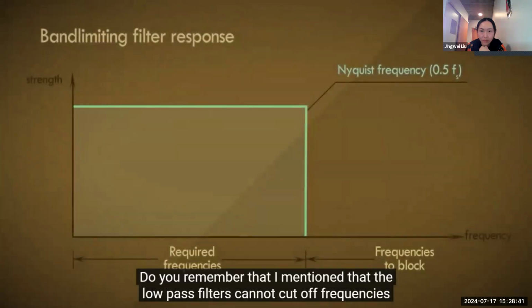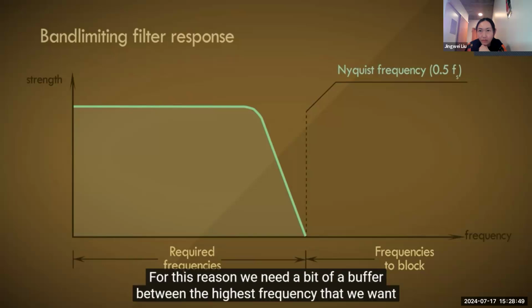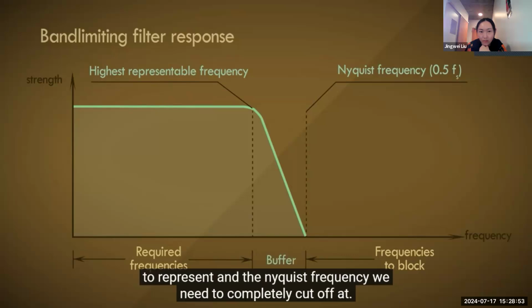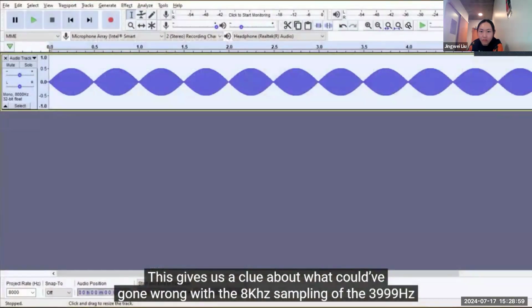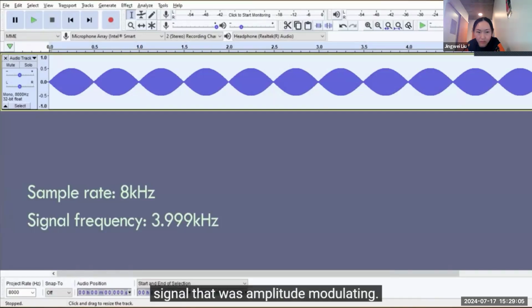Do you remember that I mentioned that the low-pass filters cannot cut off frequencies exactly at the Nyquist, but would require a smooth ramp? For this reason, we need a bit of a buffer between the highest frequency that we want to represent and the Nyquist frequency we need to completely cut off at. This gives us a clue about what could have gone wrong with the 8 kHz sampling of the 3999 signal that was amplitude modulating.